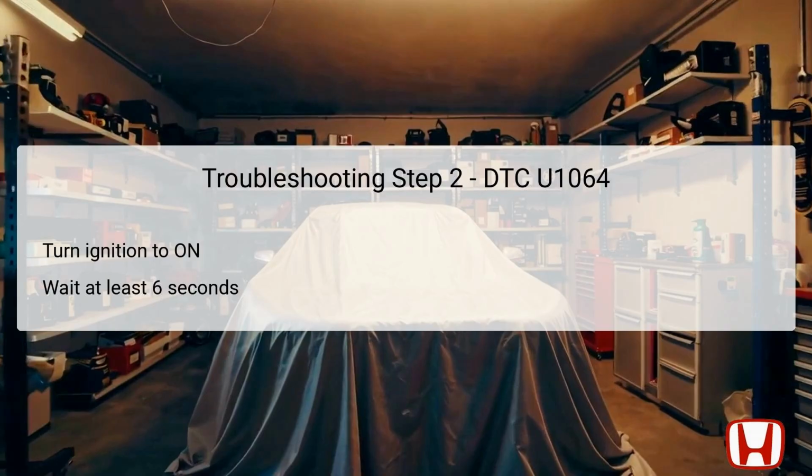This verification helps distinguish between an ongoing fault versus a temporary glitch that has been resolved by merely resetting the system. After allowing sufficient time for the vehicle systems to initialize, this step involves checking for diagnostic trouble codes again, using the Honda Diagnostic System, HDS. The presence of DTC U1064 indicates that the communication issue is still present, necessitating further investigation.